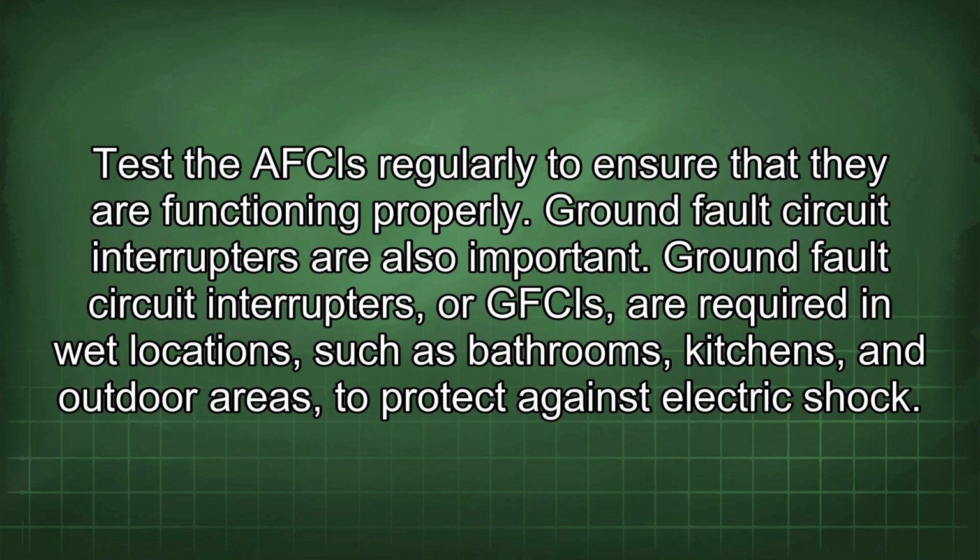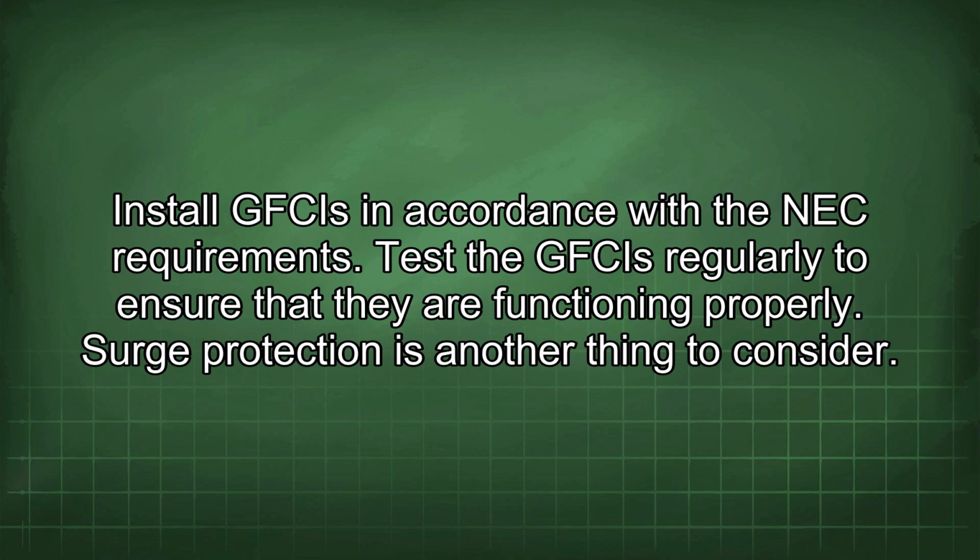Ground fault circuit interrupters are also important. Ground fault circuit interrupters, or GFCIs, are required in wet locations such as bathrooms, kitchens, and outdoor areas to protect against electric shock. Install GFCIs in accordance with the NEC requirements. Test the GFCIs regularly to ensure that they are functioning properly.